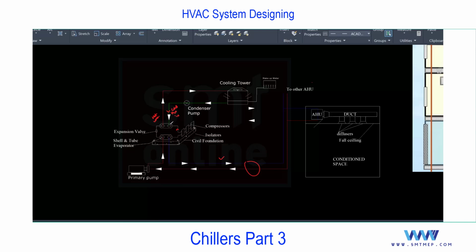I'm not saying chill water. Chill water you'll find on this side. Here is the cold water, which you can get from the cooling tower. So cold water in, extracting the heat from the refrigerant. And if you talk about the standard temperature for this cold water in, it is 81 degree Fahrenheit, and the return is 90 degree Fahrenheit.